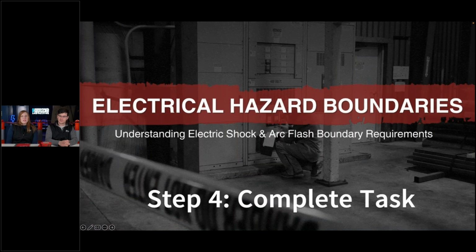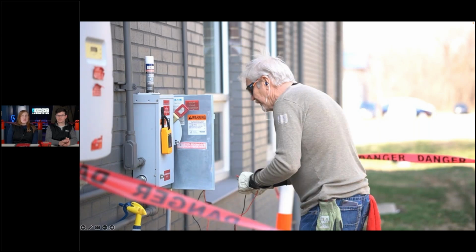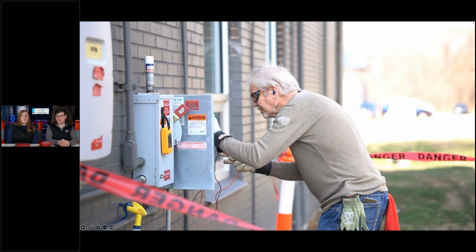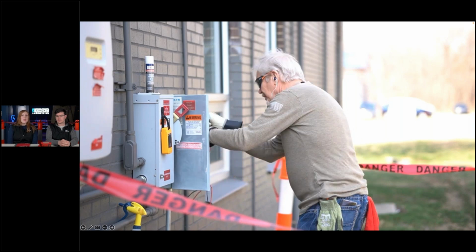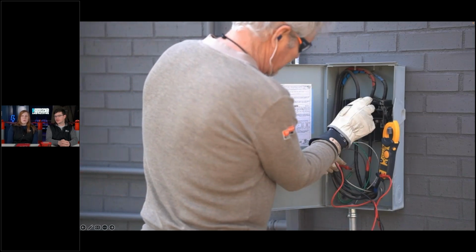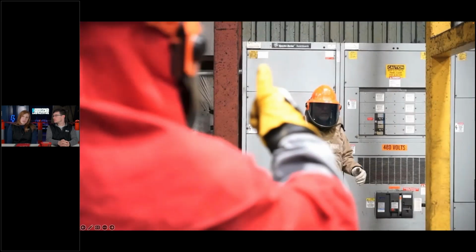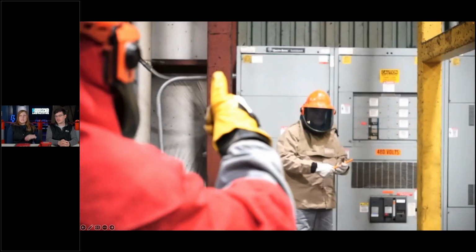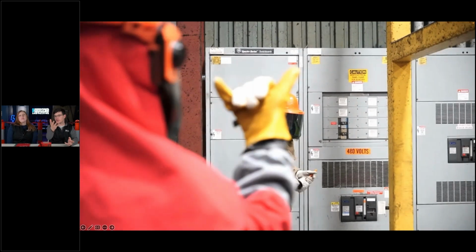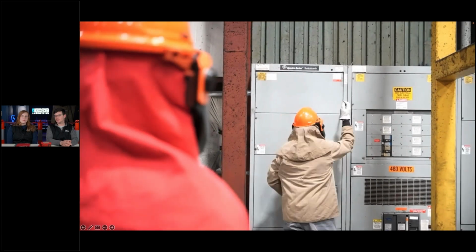All right, so you got your boundaries established, you got your PPE on, then you can get to work. And in this example, all he's really doing is verifying absence of voltage, but you see he's got the PPE, he set up his boundaries, people cannot approach closer than a safe distance just to verify that it is in fact dead before he does his servicing or maintenance or whatever he needs to do. And once he verified the absence of voltage, he could have taken away that boundary. He can take his PPE off. They got a buddy system working together. Right. If something was to happen, you got the buddy system there to help.